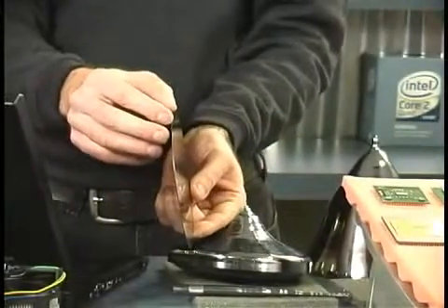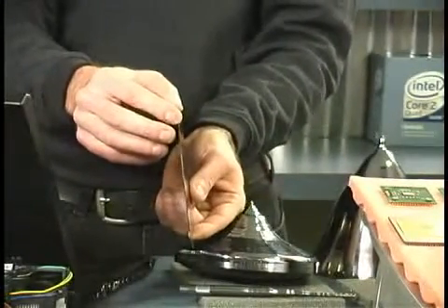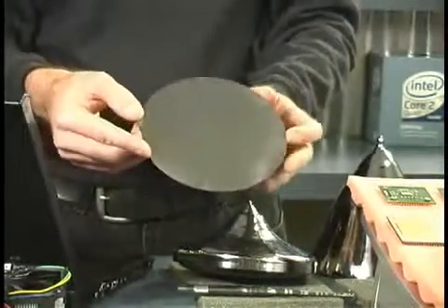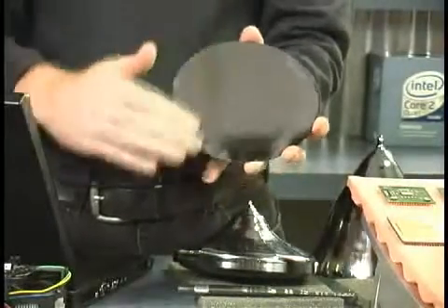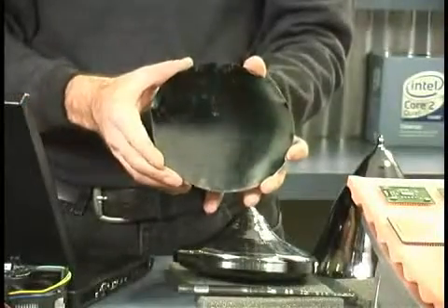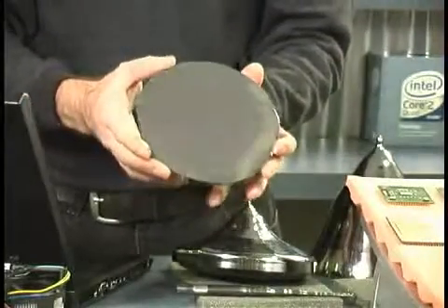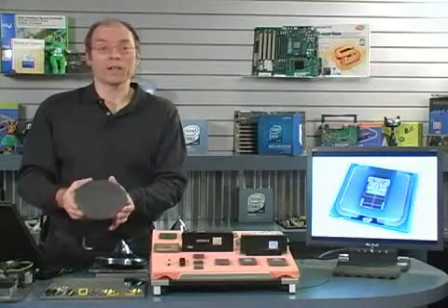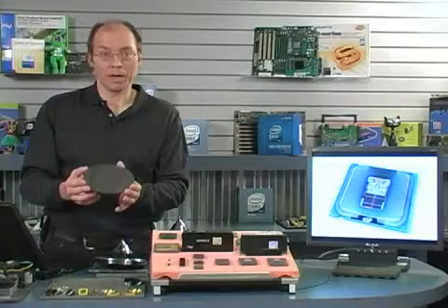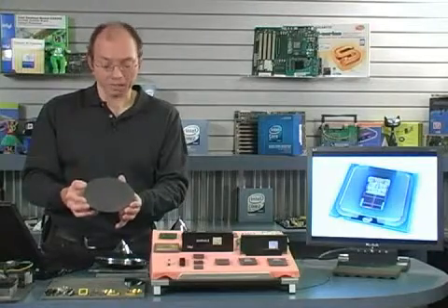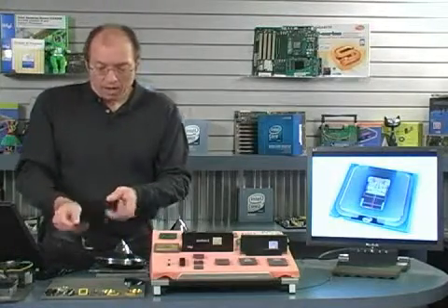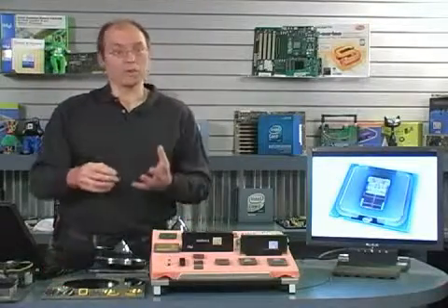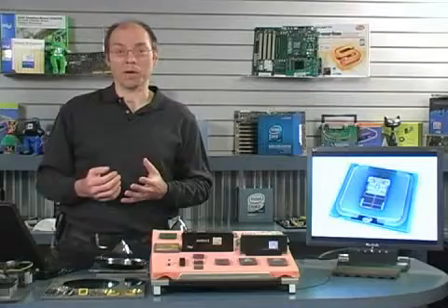It's less than a millimeter thick. Thousands of these usually come out of one single crystal. Now, the wafer would then be polished to an absolutely flat surface, better than most mirrors, a mirror polish. And then what we have is called a wafer, and this is the raw base building material for making chips. Now, what happens is the wafer is put into a photolithographic process.